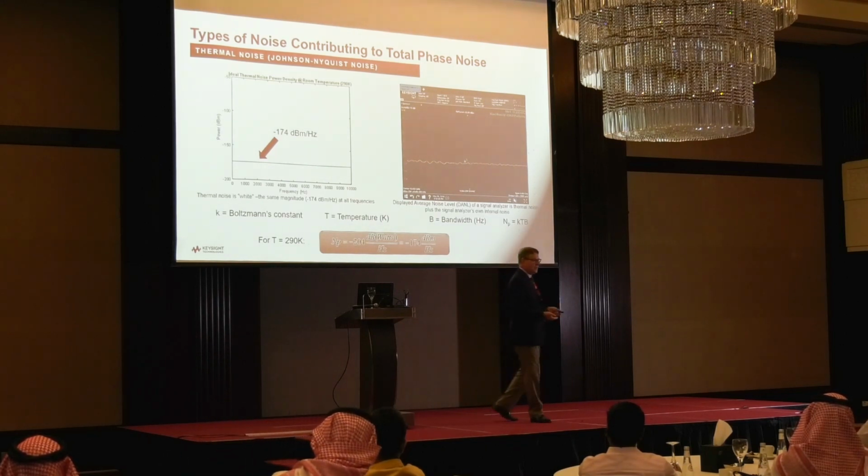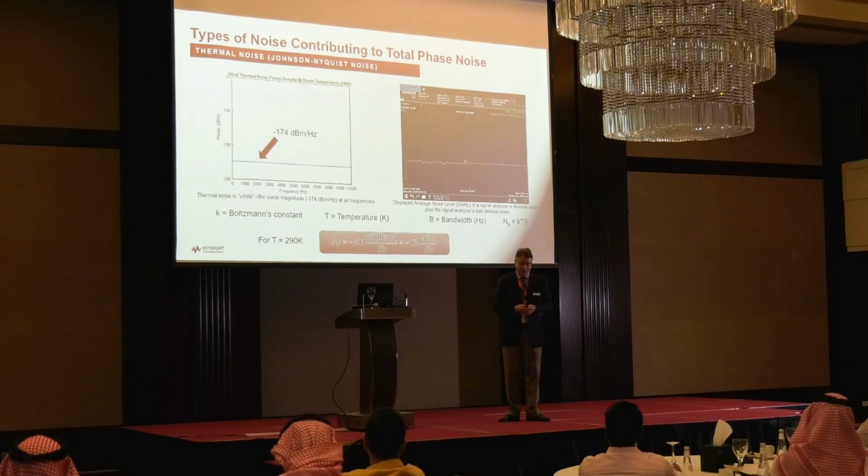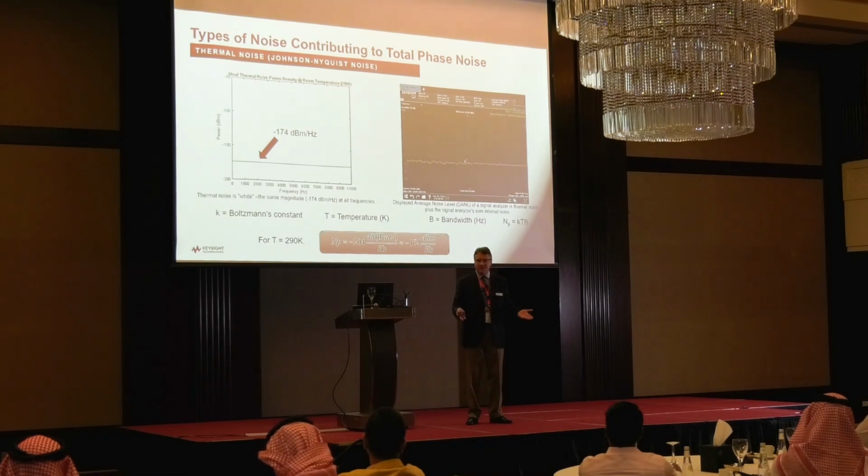All right, so we talk about KTB as being typically the best sensitivity that you could ever reach in a spectrum analyzer. Of course, if you had it super cooled and were making measurements at lower than 290, you would be able to measure even lower absolute power levels. But for most lab environments, most of our applications, minus 174 is the practical limit.